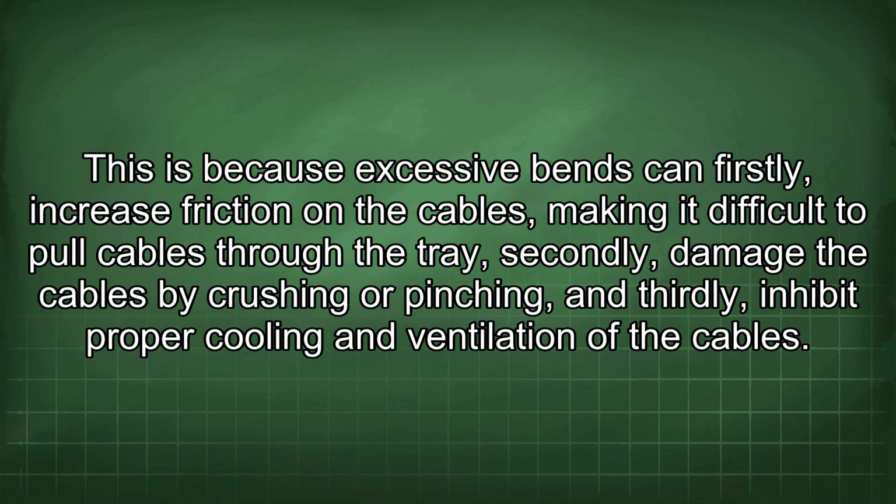This is because excessive bends can, firstly, increase friction on the cables, making it difficult to pull cables through the tray; secondly, damage the cables by crushing or pinching; and thirdly, inhibit proper cooling and ventilation of the cables.